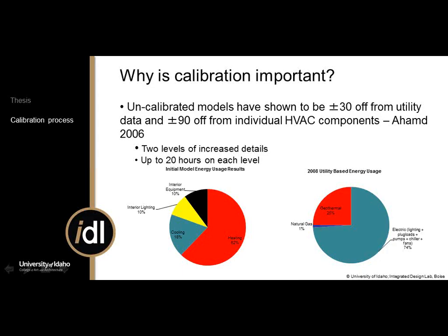And the second level, they took another 20 hours to define more specifically their buildings, and this included the thermal mass, site-specific values for occupancy, equipment, lighting, detailed surveys, as-built definition of the different HVAC systems. But what was interesting is that as they defined more of their parameters, their uncertainty increased to the high 20s, the high 80s over here. So that's an interesting thing.